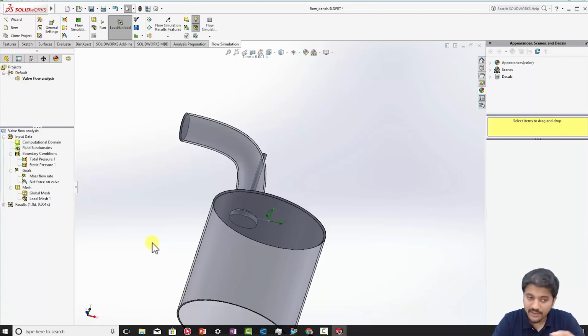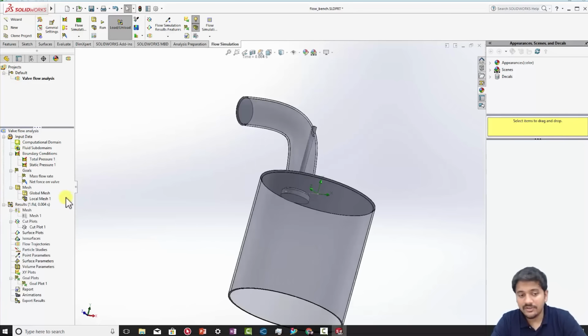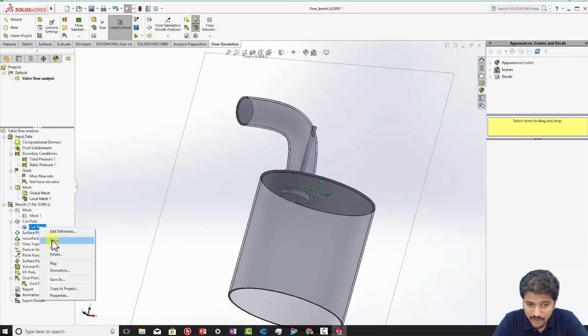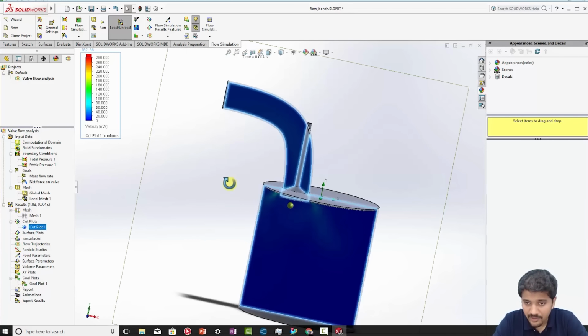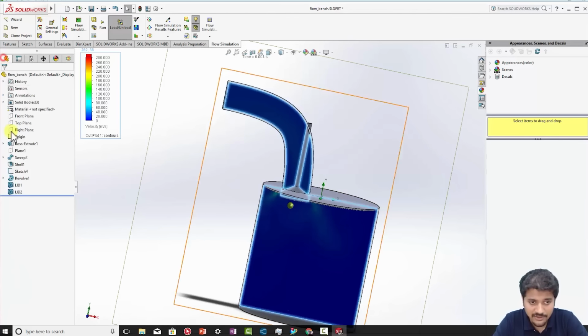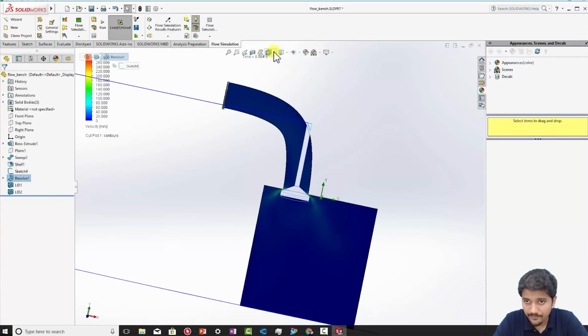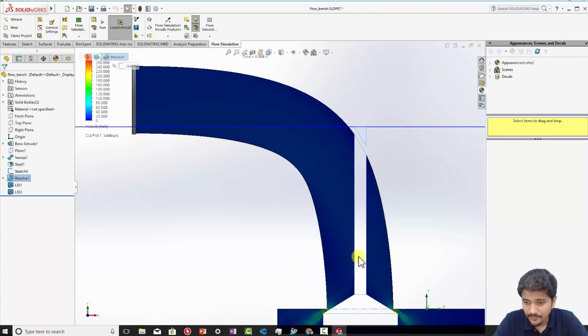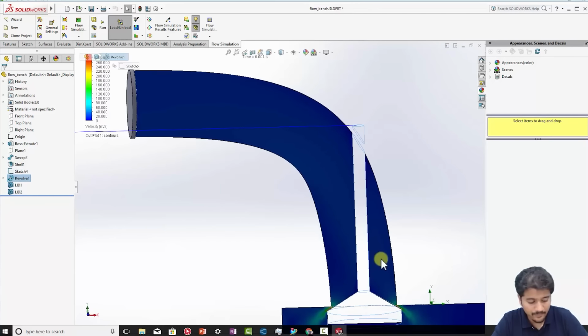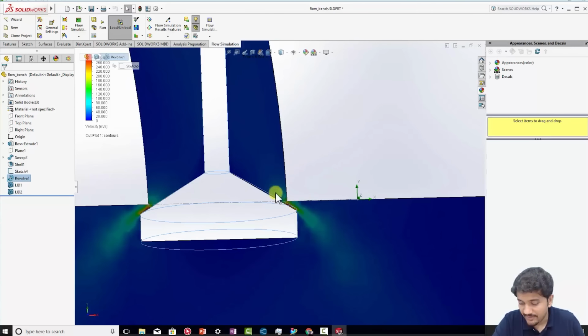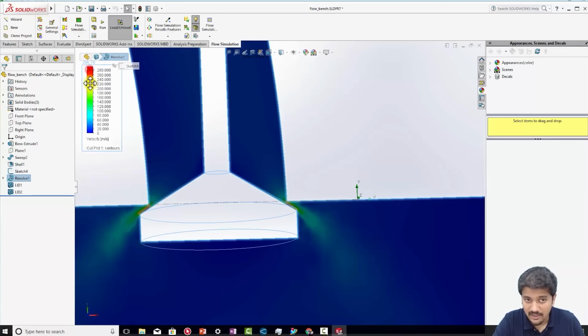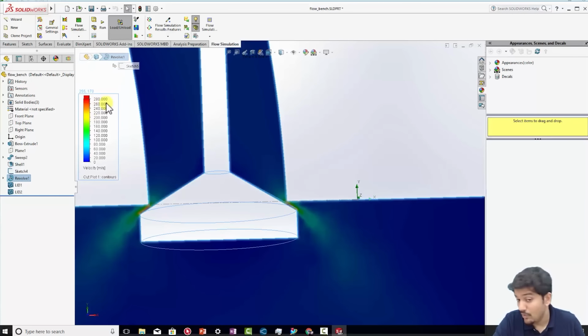Now, I'm loading the results in this case because I've already run the simulation. So in this case, I have results after 0.004 seconds. So let's take a look at maybe the cut plot. Right. So here you can see that I'm showing the cut plot, and I'll just go back here and hide the engine geometry. There you can see that there's a gas jet that's coming out, and the peak velocity is around 280 meters